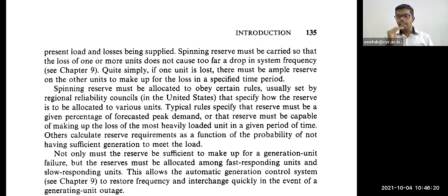For starting the second stage, they will spend at most 10 minutes to start all the penstock valves and all. So by that time they will simply switch on the spinning reserve generating units for 10 minutes so that it meets the demand. That spinning reserve unit will be your diesel generator.